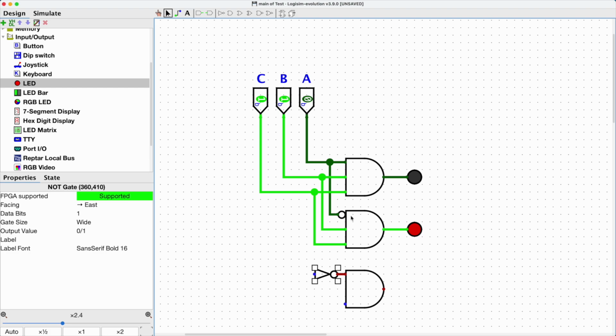And this inverter is just indicated by a little circle. Okay. So it's just a different nomenclature, right? It depends on where you need this inverter to be, right? If you are just inverting the inputs, then use the properties and set the negation on the inputs to each gate itself. That's the cleanest way to do it, right? This just uses a lot more space. Okay, and that's your intro to Logisim.